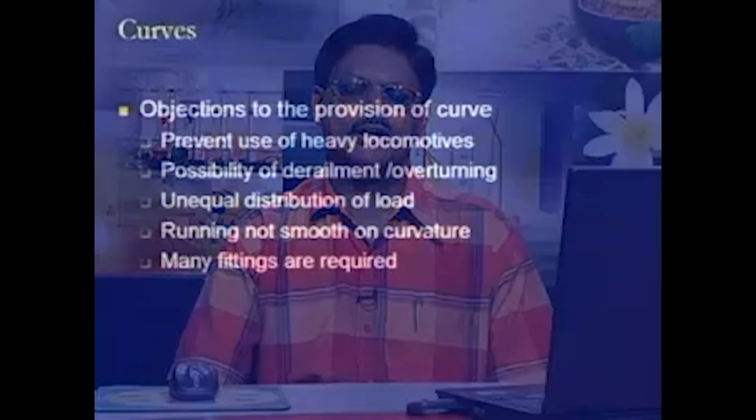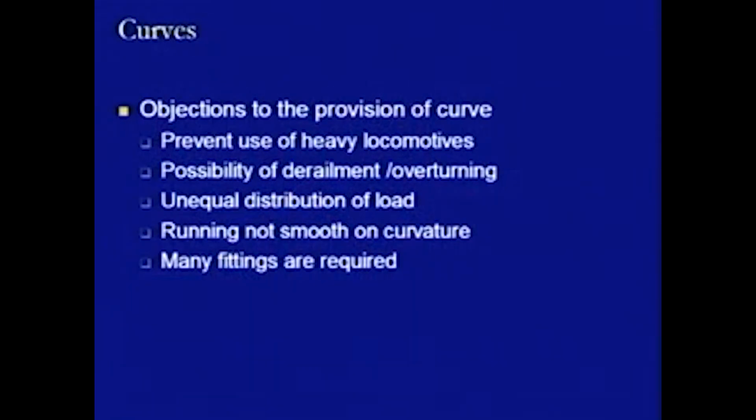And further, when we have curved tracks, more fittings are required, so that the effect of centrifugal force, due to which these rail sections may go out of section, go out of alignment, or go out of gauge, is resisted and they remain in position. To make them remain in that position, more fittings are needed or provided.